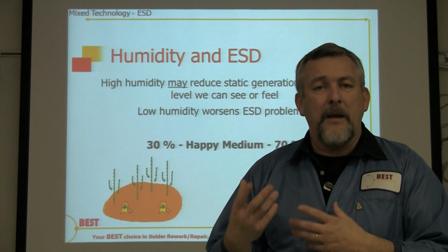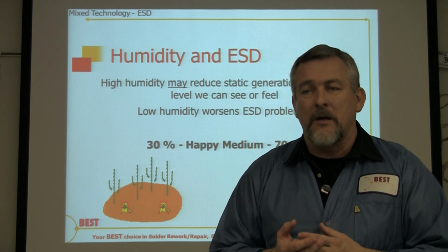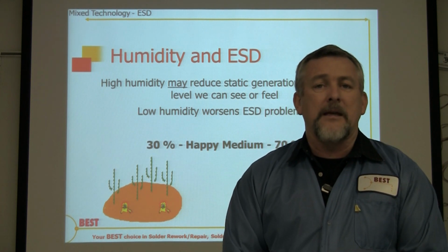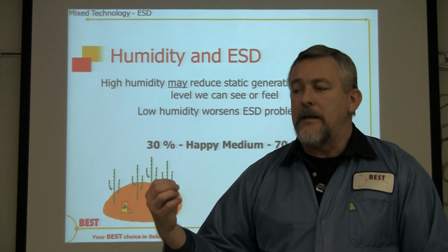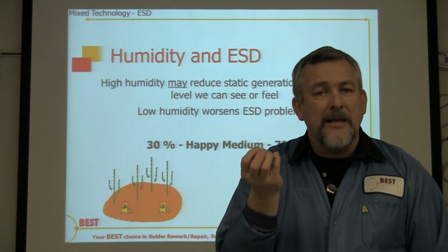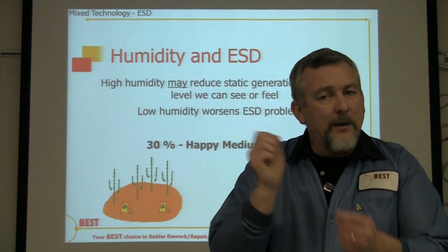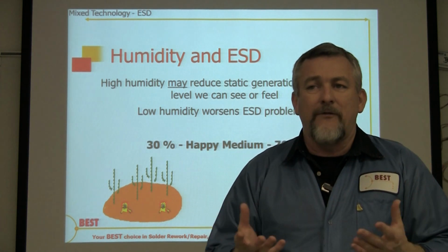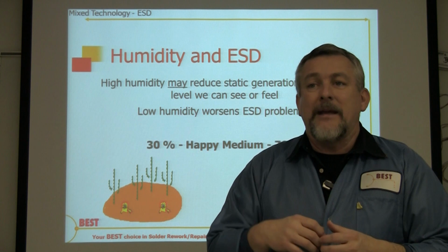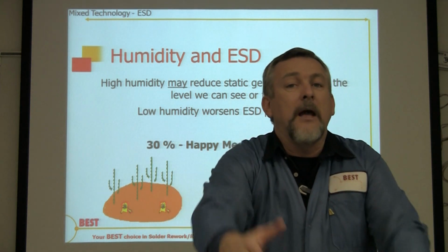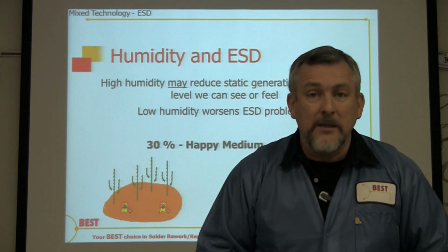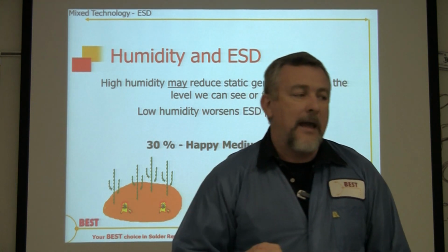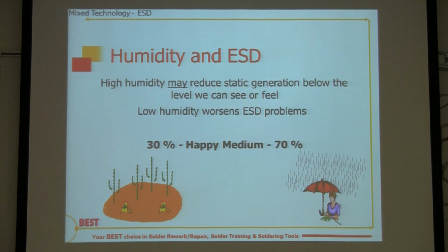A lot of the components that are made of plastics are very sensitive to moisture. A prime example in our surface mount work, one of the big ones, is the chip capacitors. Moisture gets inside that ceramic little guy, and when you hit it with an iron, as small as it is, that moisture evaporates. In other words, it turns into a vapor. That expands, right? It can crack or fracture the inner layers, and you're not even aware of it. You replaced a part, but that wasn't even what caused it. It was you hitting that iron with it, and it happens just like that. So be very, very careful.